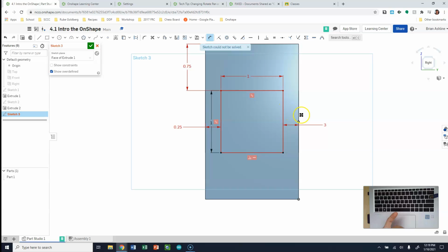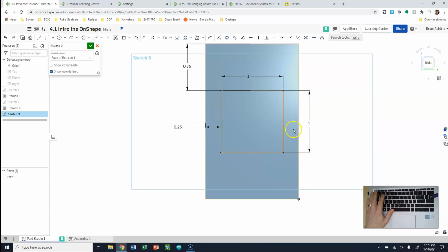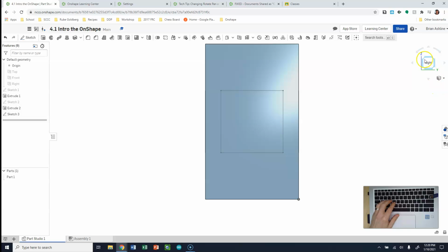This thing is only 1.5 inches wide, so it's like, hey, you can't do that. There's an error here, okay? And that error is that I've just created this dimension, which is unnecessary. It's over constraining the object. So again, we've dimensioned this block. Try that on yours.